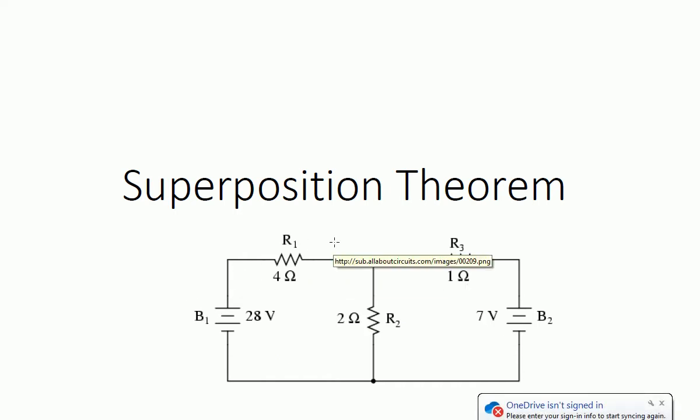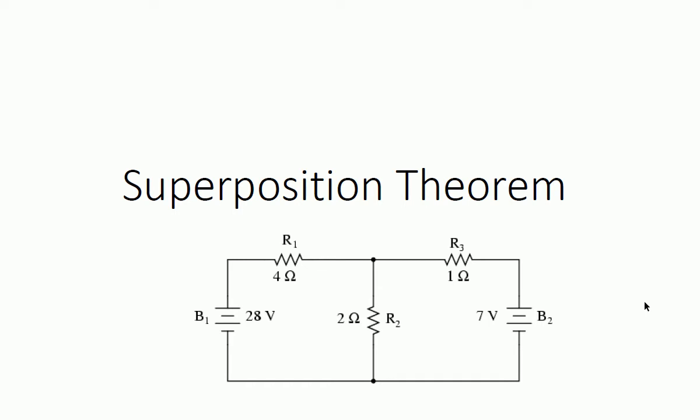Again, just to remind you, what is an internal resistance and what does it stand for? When you connect a load to a battery or to any power supply, what you'll find almost inevitably is that the voltage is going to drop a little bit. Depending on the current you draw out of it, the bigger the current, the higher the voltage drop. Even with a car battery, let's say it is at 12.5 volts, and you turn on your lights, the battery itself is going to drop down to about 12 volts, whilst there's a current of about 4 or 5 amps coming out of the battery.